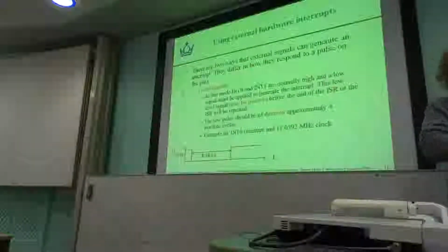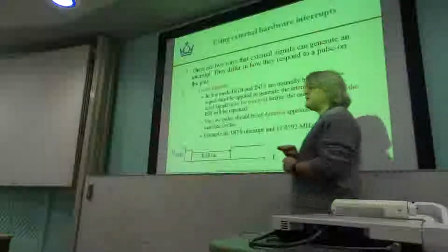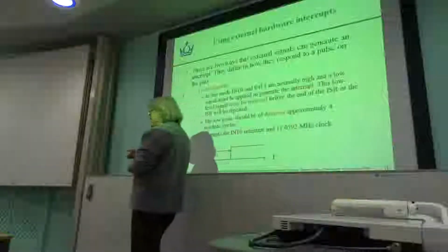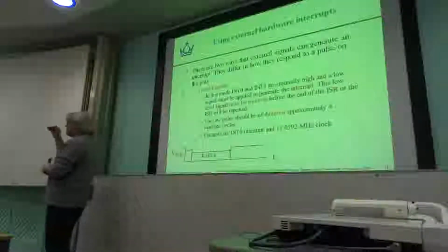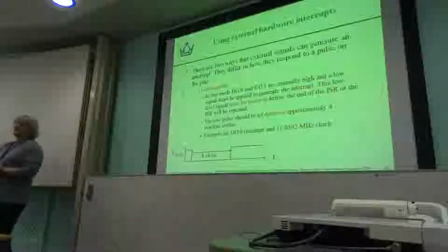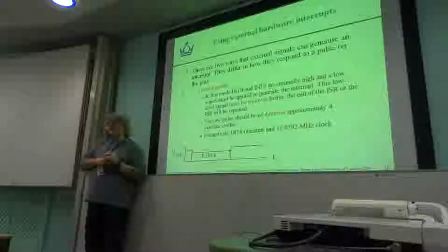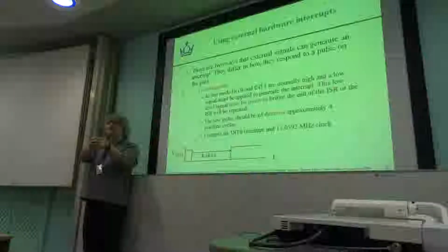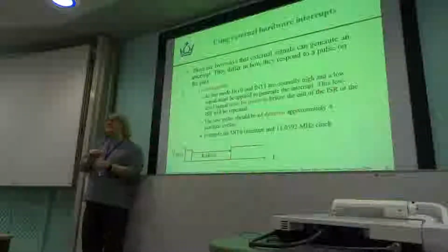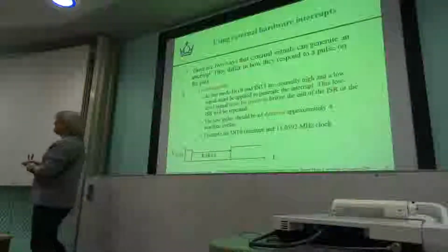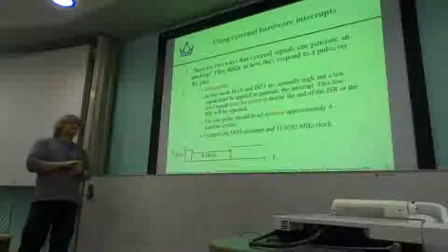We often use interrupts in real-time systems where if something happens, we don't want to have to wait a long time to respond to it. And the nice thing about interrupts is, as soon as one of those interrupts happens, you take control of the program, pause it, and go somewhere else and deal with the interrupt straight away. So you can end up with a very responsive system.